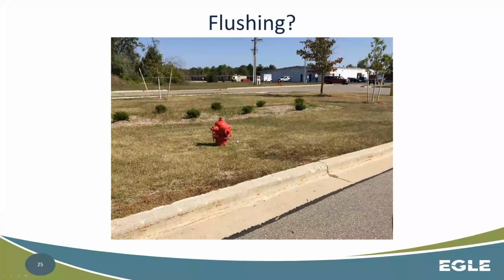The elevation and location of hydrants may change what you have to do to properly flow or flush a hydrant. As you can see, this one's elevation in relationship to the curb back is not very good. And you can see they've actually tested that, right? If you take this pumper nozzle cap off and open this up and just blow it straight out, it's going to hit this curb back, erode this curb back, and you might lose your curb altogether. So this is not an ideal situation for a full flow out the pumper nozzle to atmosphere, because it'll erode this ground and cause all kinds of problems.